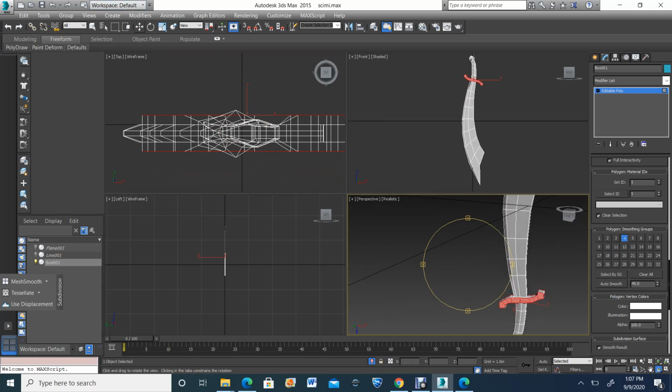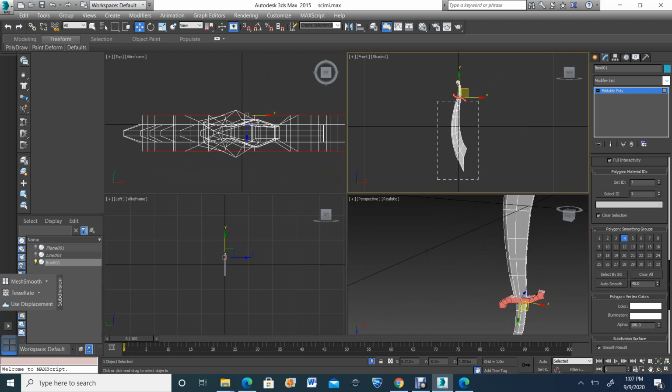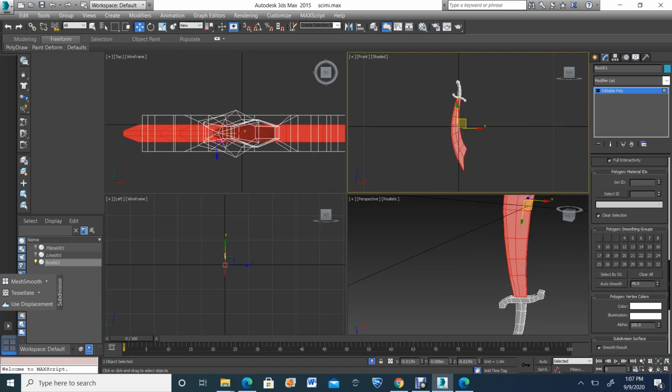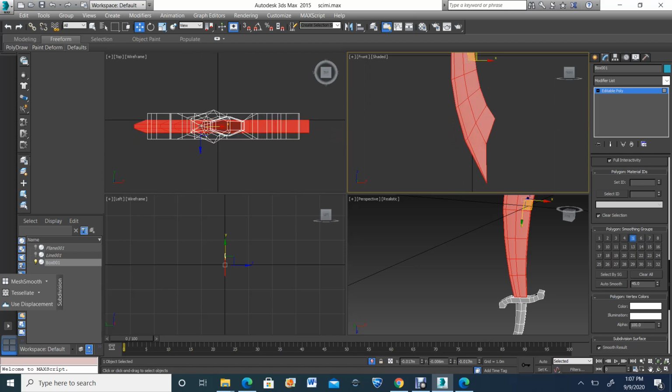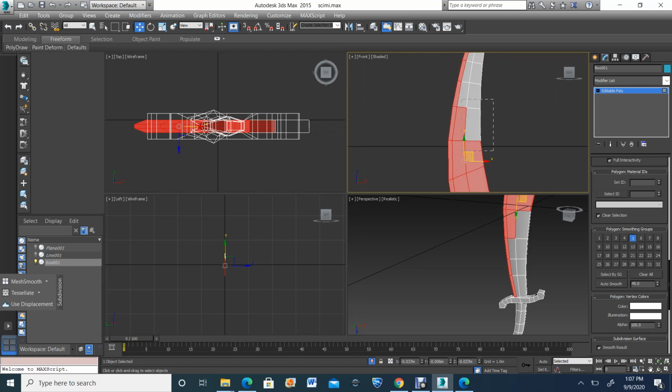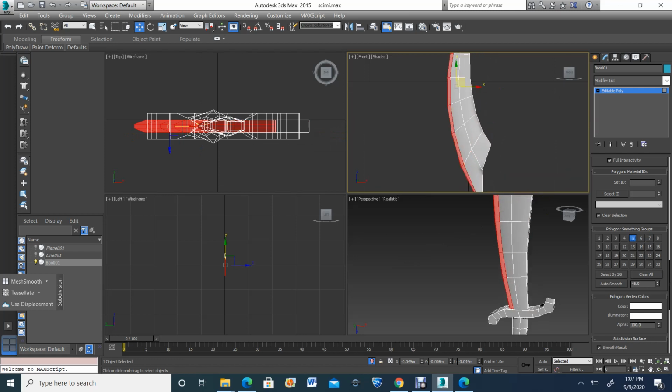And then I'm going to do the same for the blade as well, to get the edge. So I'm going to select all of this, clear that, give it a smoothing group of 5. And then to give it some sort of variety, I will unselect these, and to unselect is Alt while dragging. So as you can see now, that's a whole different selection. Take this, make it into a different smoothing group.